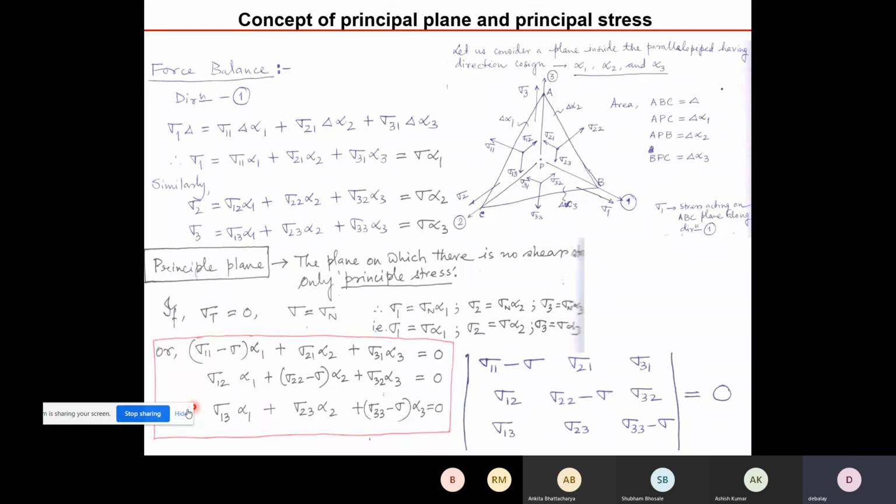Similarly, if wind is blowing in the transverse direction, say direction 2, then the wind velocity and the wind force will determine the stress sigma 2. So these will be real values, and based on those real values, I want to derive the principal stress. Because once I can derive the principal stress, further mathematics will be easier to deal with.